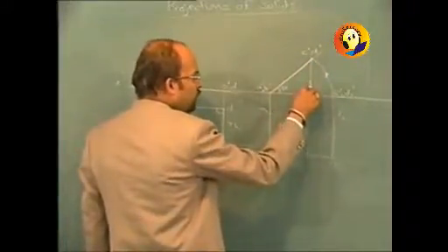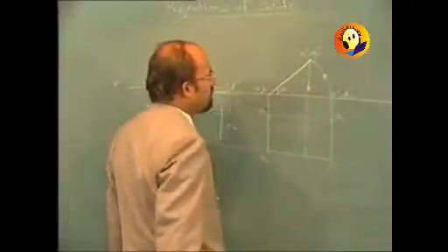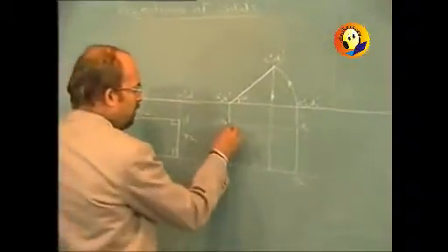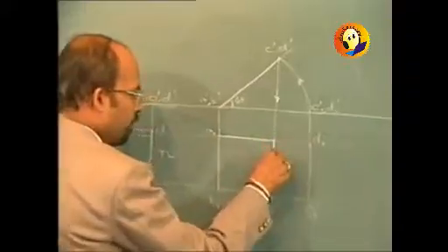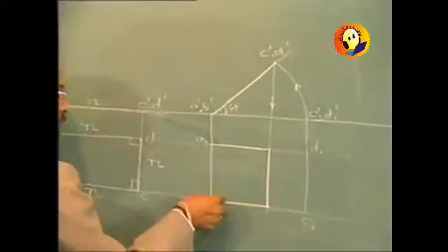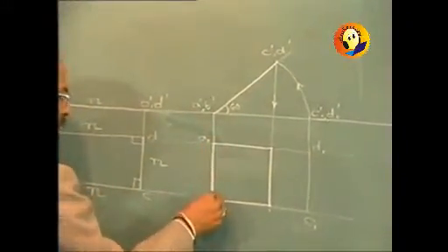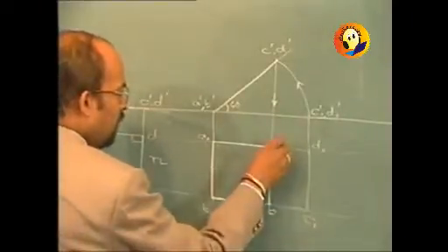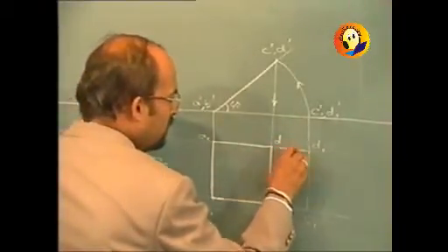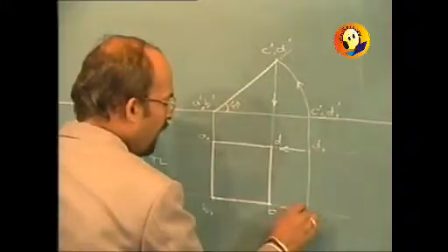We are dropping the projector from point C and D in the elevation, and we can complete the plan, which will be A, B, C and D, remembering the fact that rotation in one view is movement parallel to XY.